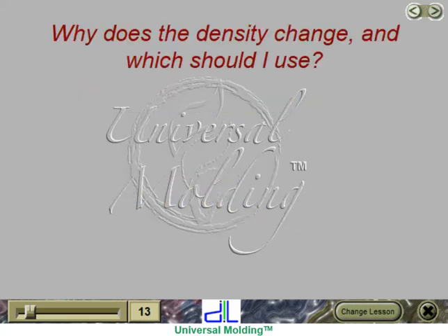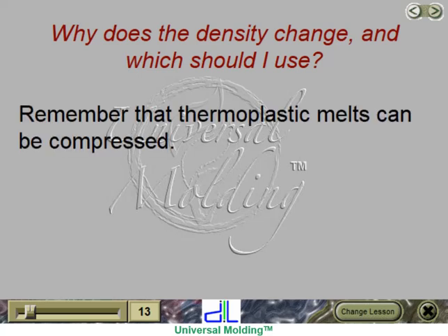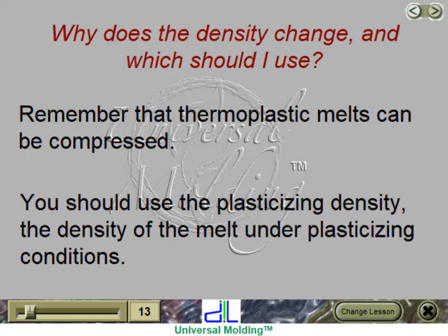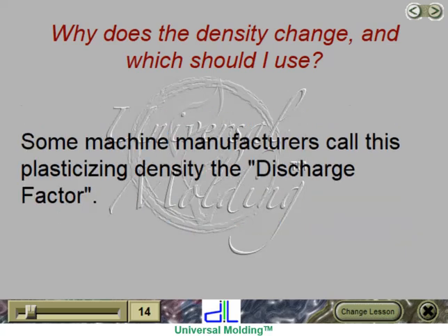Why does the density change, and which should I use? Remember that thermoplastic melts can be compressed. You should use the plasticizing density, the density of the melt under plasticizing conditions. Some machine manufacturers call this plasticizing density the discharge factor.